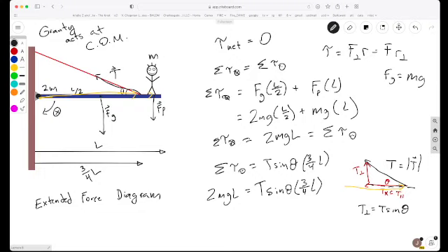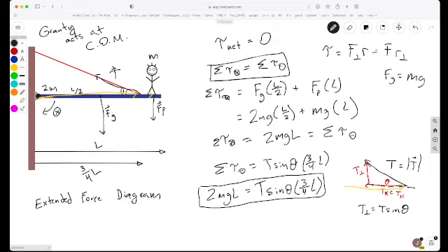This is just when we solved this top thing here. So this turned into this when we evaluated it. I'll say we didn't really use any signs here. We could think about torques as positive or negative, but I think it's much easier to just think about into and out of the page and keep everything positive. So then we can set one equal to the other. We know these are equal and opposite because we've said the direction of one is in and the direction of one is out.